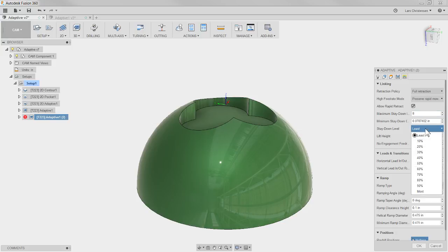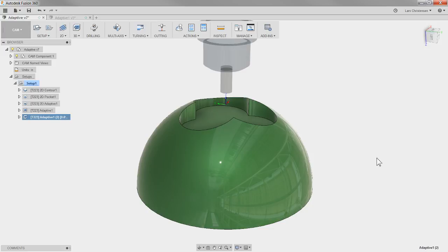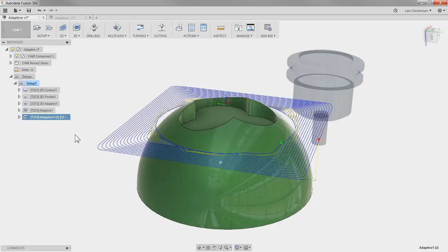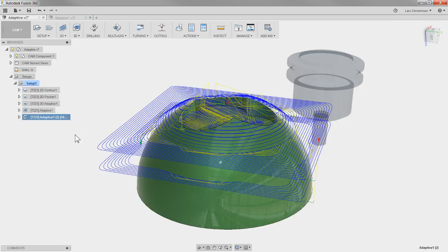And let's just set this one to 50%, which is kind of my default to go out of the gate so it doesn't take too long to calculate. Still going to take a little bit longer to calculate. But what the cutter will do now is, again, remember from the beginning, it is the model versus what stock we have. And it will now find a shorter distance between the next path and not wrap it that much.